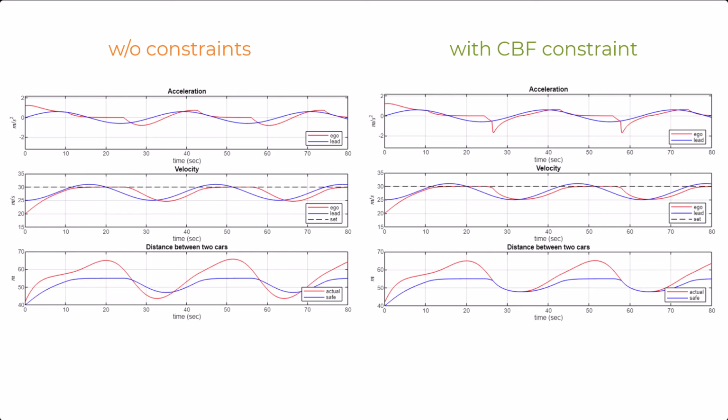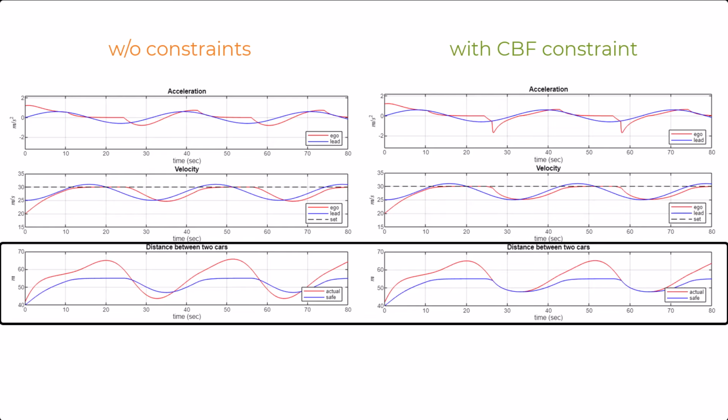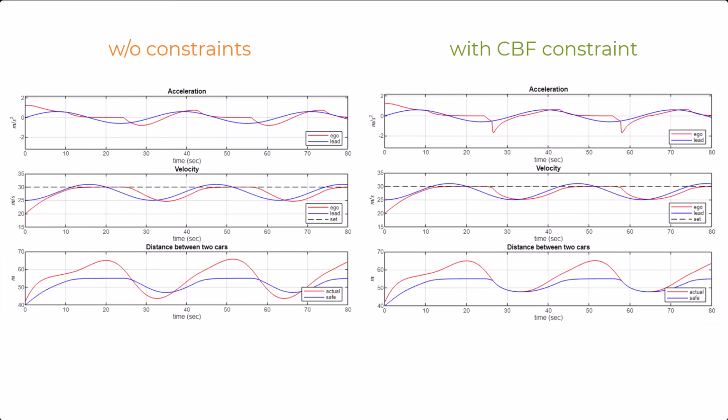We can now see that during the driving scenario where the minimum distance between the vehicles is about to be violated, the barrier certificate enforcement block steps in, solves for an optimal control input that ensures that the relative distance between the cars never drops below the minimum threshold. So you can see the modified acceleration commands during these time instances here.